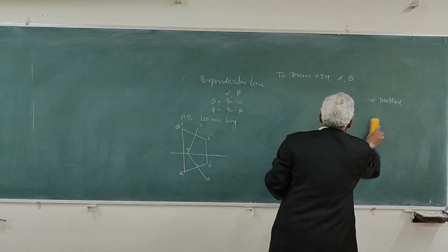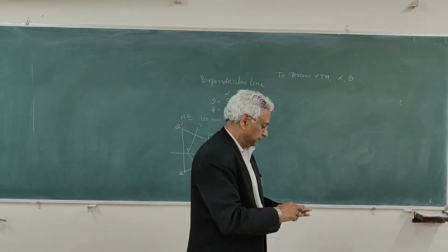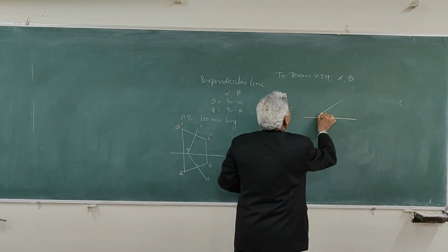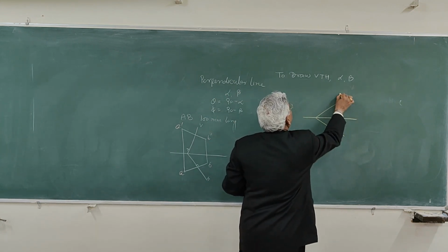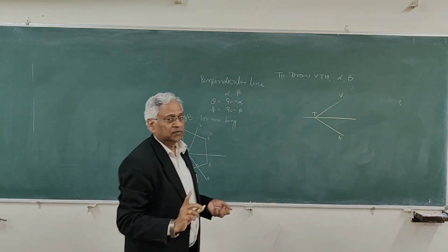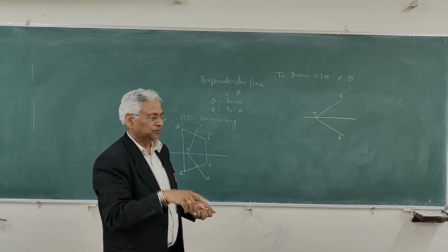Now here you have four angles. The angles made by the vertical trace and horizontal trace with the ground line, that we call eta and zeta, and the actual angles made by the plane, alpha and beta. If any two are known, you can determine the remaining two.